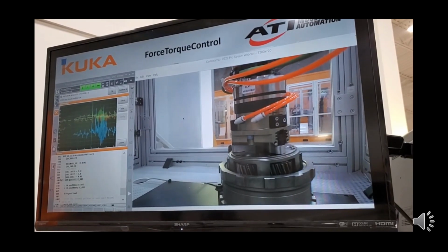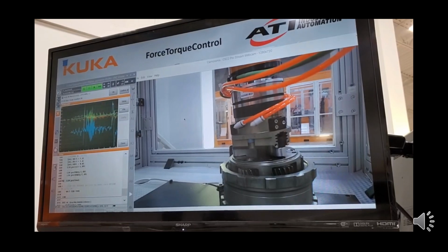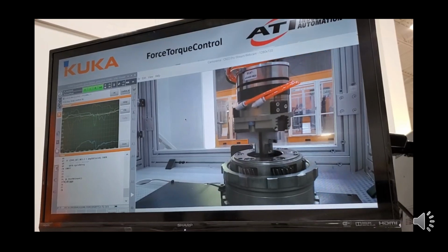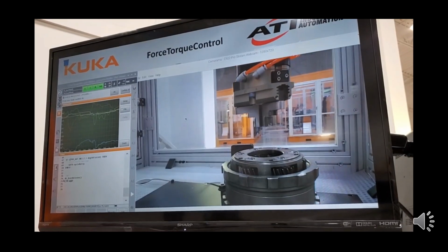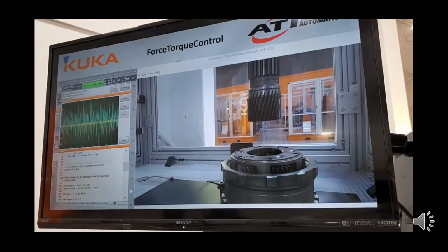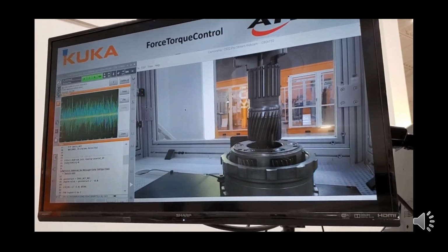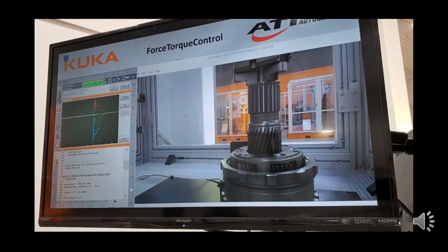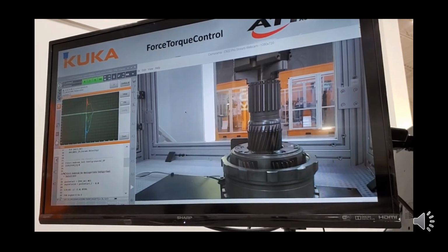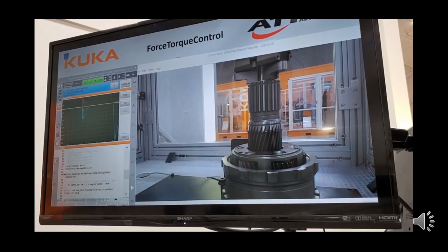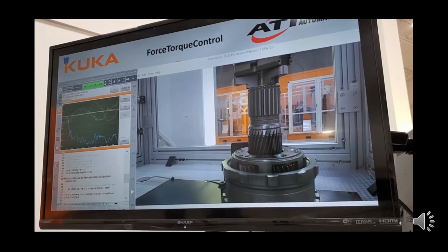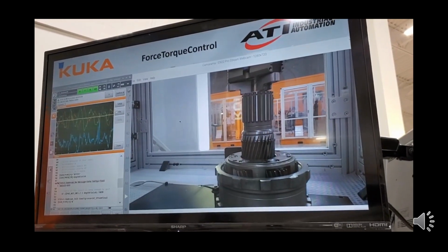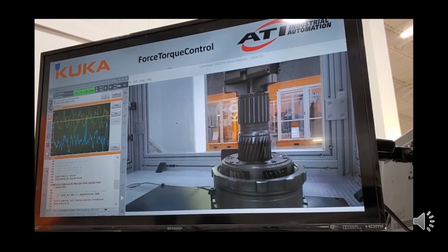These sort of behaviors work together to generate a human-like capability that can get the independent gear pieces to align and mesh properly. The process also implements a sensing behavior to feel when the gear drops into place, so the robot knows the task is complete. You'll notice in the upper left corner the RSI monitor graph, which is showing a live feed of the process forces. This provides excellent feedback for debugging and process monitoring. It's a very valuable tool that helps to correlate between visual observations and the control behavior of the robot.